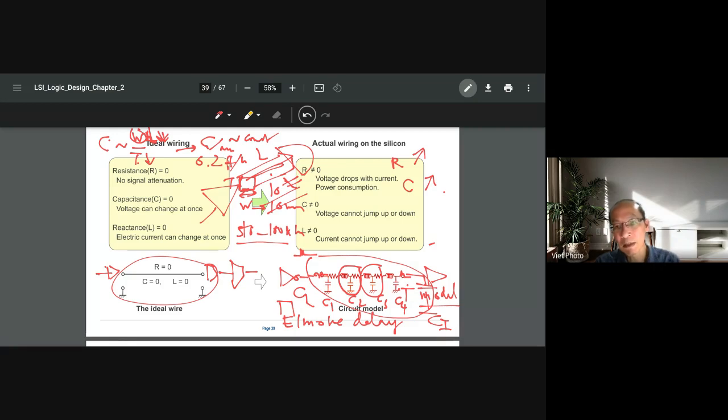We have frequency going up to 4-5 gigahertz in the Intel chip, but the length is reduced because of scaling. The wire length is like the distance between one gate and another. When the logic gate is smaller, they pack more, so you can imagine that the wire length is smaller. Because of it, inductance is not an issue in the design.